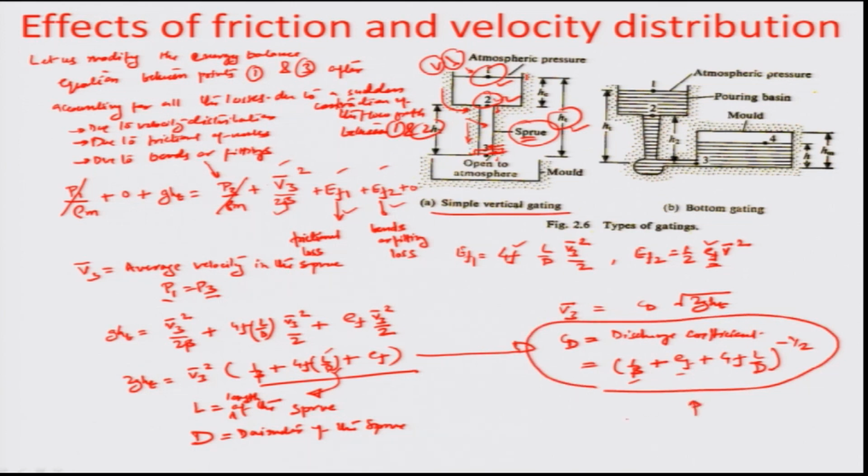And as I will show you in the following iterations, the discharge coefficient here can be generated in an iterative way, because at the outset you probably just have a first guess of the Reynolds number, and that may not be the accurate velocity, because the velocity has to go through all these different terms. So the earliest assumption that you can make, if there is no loss factor, that is C_d equal to 1, is that V3 converges into root 2 g h_t, which is in fact the same term as you had seen in the analysis where we neglected the frictional effects.